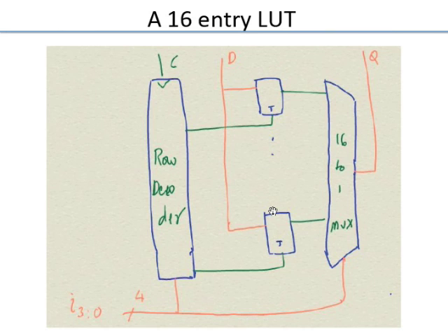Now, when you shift serially, you are disturbing the contents of the memory. Suppose I want to write some 4th location. How do you do it? If you shift it, everything gets shifted. So you have to take care to make sure that after all the shifting is done, only the 4th entry has changed, and everything else has remained where it is.